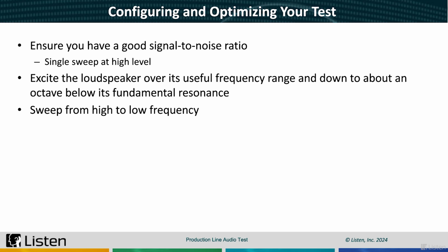In terms of a test signal, I'm a big fan of the sweep. This is our optimized step sine wave sweep. It's been optimized for speed, noise rejection, and accuracy, and it can be as fast as a log chirp and even sound like a log chirp, but without the added complexity of time windowing. Let's take a listen.